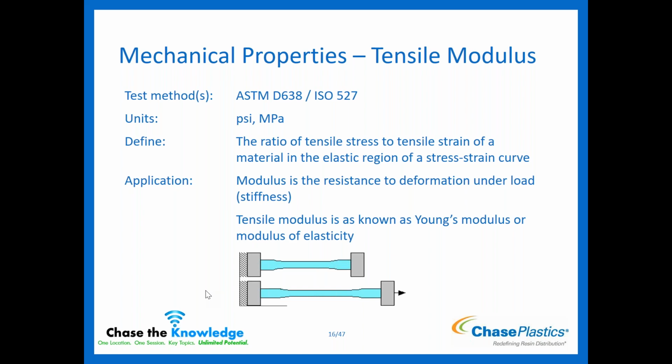Some other terms you might have heard of: Young's modulus, modulus of elasticity. Those are other terms that we use for tensile modulus. So if you're doing some FEA work or something of that nature, you might see that those values are asked for. Just know that that references tensile modulus. You'll also notice we talk about flex mod. Just note that really the difference is how it's being put into stress. For tensile, you're pulling it apart. So I'm pulling it in this direction, I'm pulling it apart.